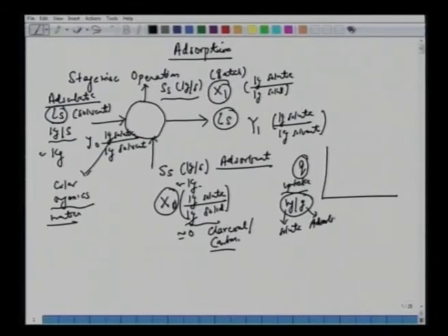We are of course using kg per kg here. And if we talk of the isotherms, then you have C, or partial pressure of the solute in the gas phase. This C would be milligram of solute per liter of solution. Here you have partial pressure, say, in atmospheres. You can also work on the mole fractions in the gas phase.